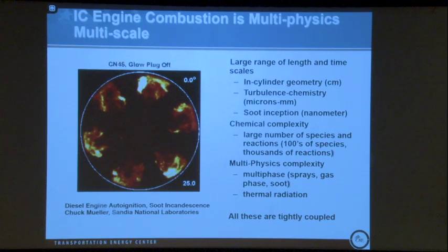And so you have to deal with sprays, you have to deal with downstream of combustion, especially in fuel-rich mixtures, the formation of soot. So you have precursors from the gas phase chemistry that allow you to nucleate soot, and then you have chemistry that describes how you agglomerate or make those soot particles bigger.